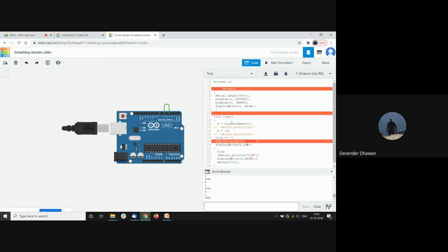Okay, so we read high, made it low. So this should come here, then made it high again. So it will keep on running in this loop only. So that is our logical error. So if it is high here, this we will not need now. And now it is fine. So now you see we are getting high, low, high, low.